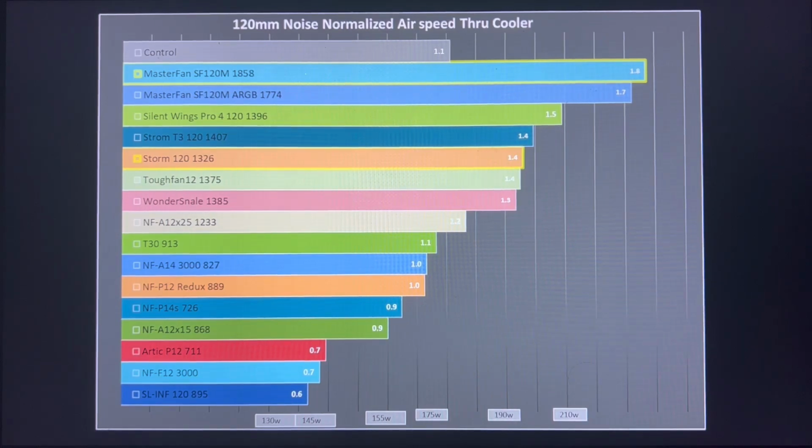But that 40 decibel reading is based off of the Noctua A12X25 running at approximately 1,100 RPM, and I just found that RPM to be particularly quiet on that fan, where I could basically not hear it with my desktop sitting right next to me on the floor and my chair, well, again, right next to it. So I chose the reading that I got from my fan as my baseline measurement point. So all these fans are based off of that noise measurement. So I would consider this the maximum speed for a fan to still be quiet.